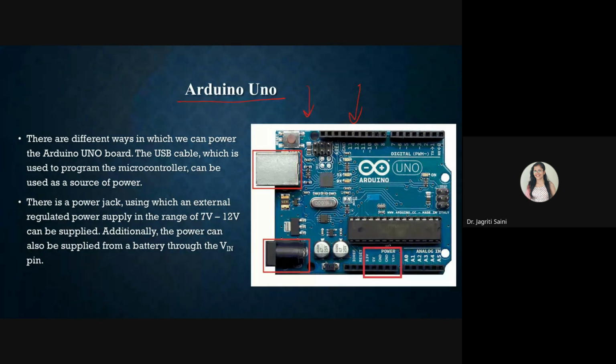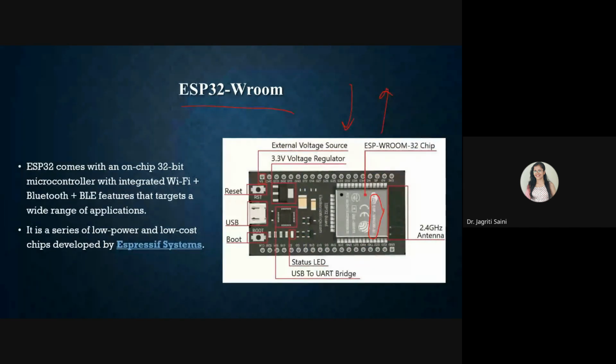A gateway you will need to connect with Arduino Uno, and then that gateway will send your data to the cloud. But here on this ESP32, it is a combination of microcontroller plus gateway. So both things you will have here. Whether you want to collect data from the field environment and side by side send it to the cloud, this ESP chip will do the thing for you.